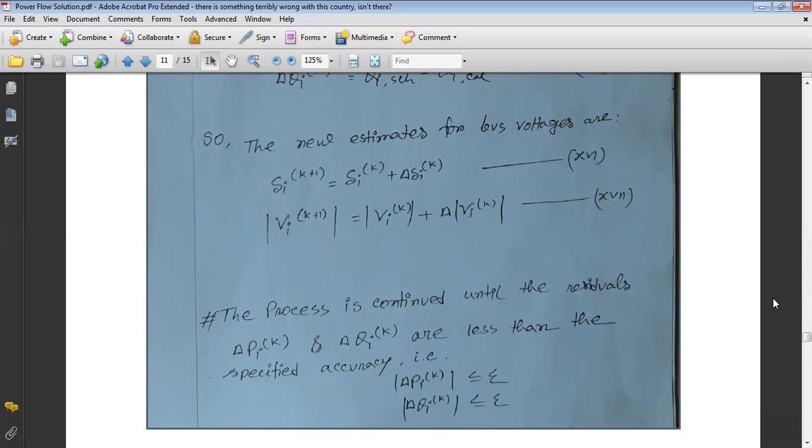And if the power mismatch matrix doesn't satisfy the tolerance level, then the values we have calculated are not our desired solution. So once again, we need to calculate the Jacobian, determine our new correction matrix, and update the values. Next, we check the power mismatch matrix using the updated value, and finally consider the tolerance level. If the tolerance level is satisfied, then the last result is our solution. And if not, this process goes on.